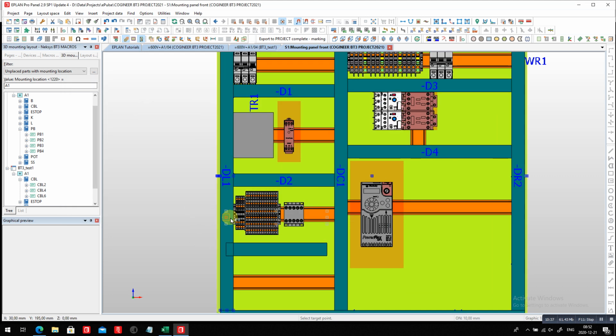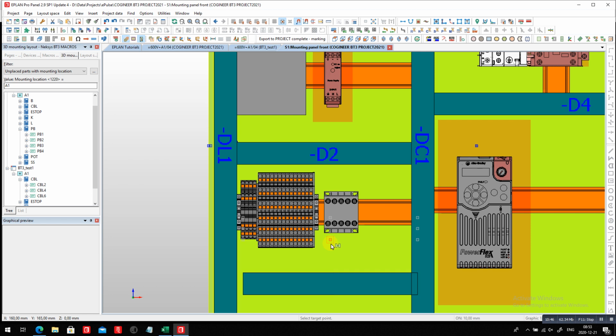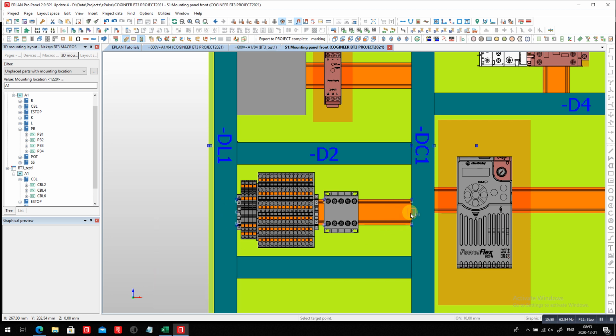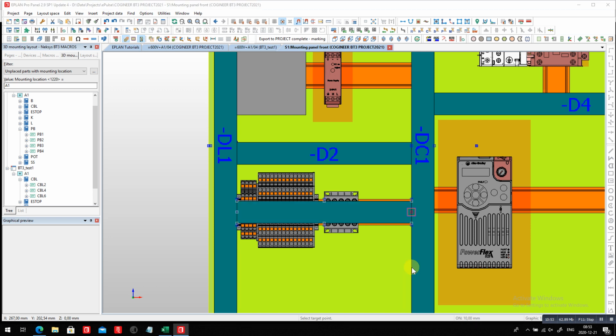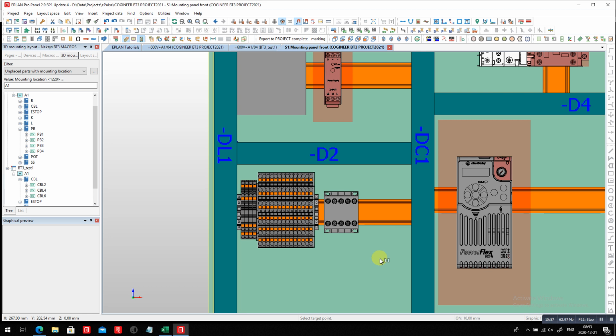Okay, that's one way you can do it. You can even change your handle if you're more comfortable, right? You can actually change the handle to the other side and say, let's go center here, 75 millimeters, like this, boom. And you just basically decided that this duct is exactly 75 millimeters from the center of that DIN rail.